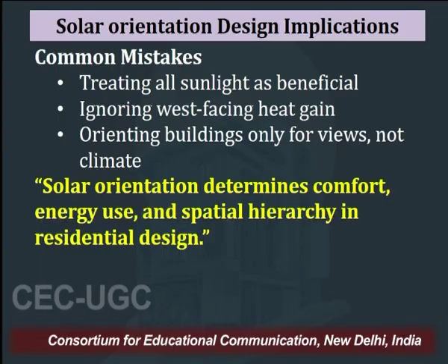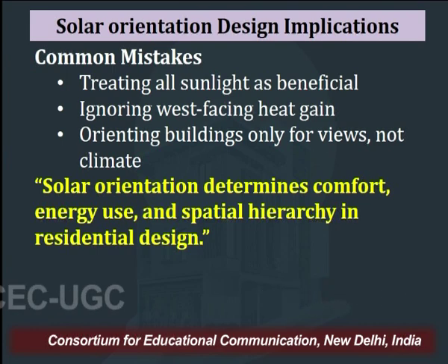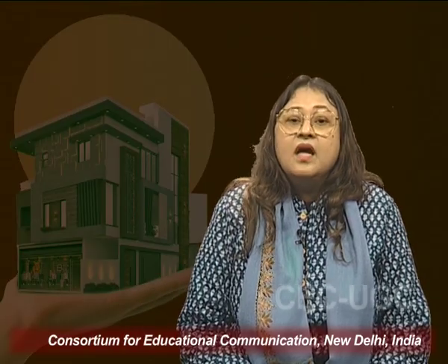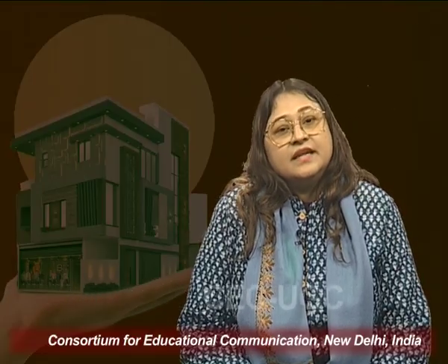Many common mistakes happen when we just treat sunlight as a beneficial aspect and ignore what is happening in the west. If we see the movement of the sun from east to west, the west facing facade gets the maximum heat gain for the maximum time, and because of that the overall thermal mass of the building will increase.